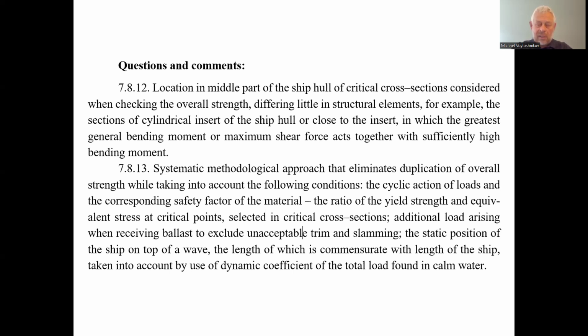So all this is the assumptions for the calculation. We have to obey the duplicity, either with no ballast but with slamming, considering an extra safety margin to exclude the possibility of fatigue failure, or we exclude the fatigue failure not with an increase of the safety margin but with the increase of the bending moment, considering the reception of ballast in the fore or aft peaks of the ship hull.